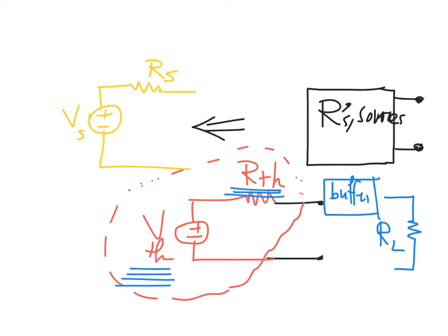In this way, the voltage at this point will be translated to the other side without any losses due to the resistances before or after. This is the main usage of this operational amplifier as a buffer.